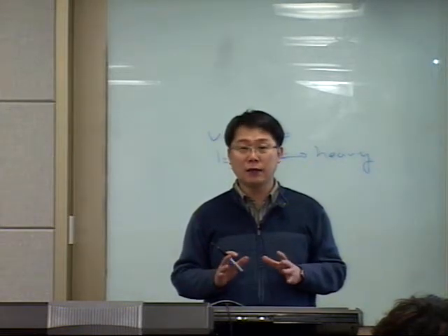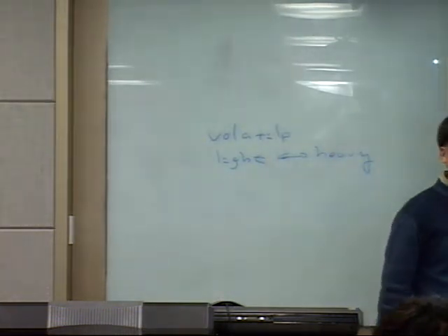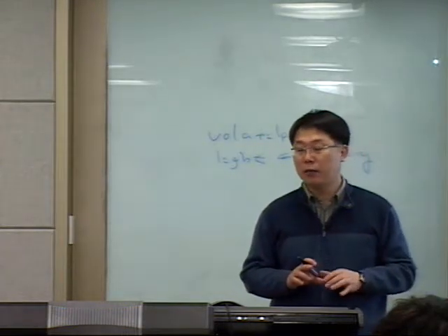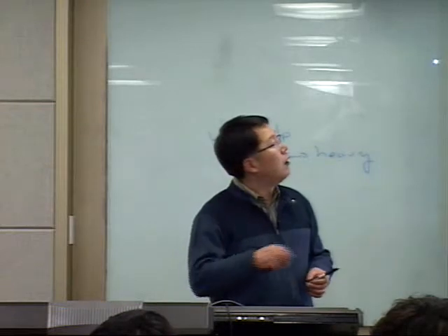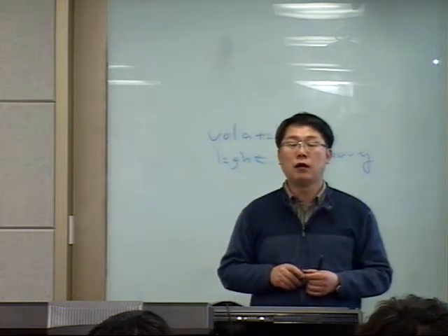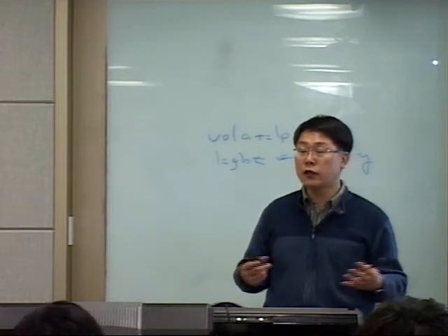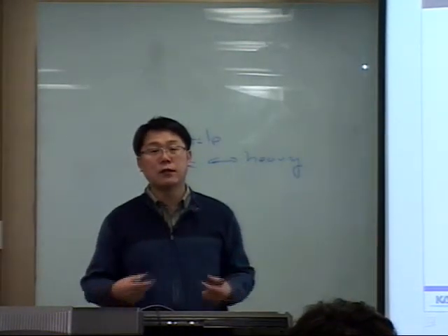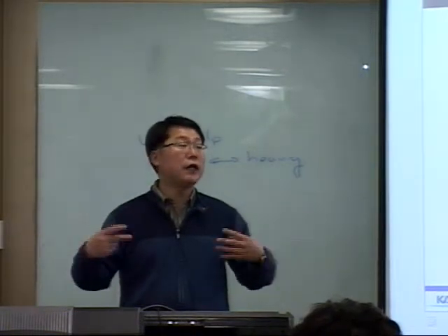One more thing is, our cargo tank is a little warm before loading. Usually it is around minus 90 Celsius before the LNG loading because there is no LNG within the cargo tank. So it was a little warmed up due to the external heat ingress.